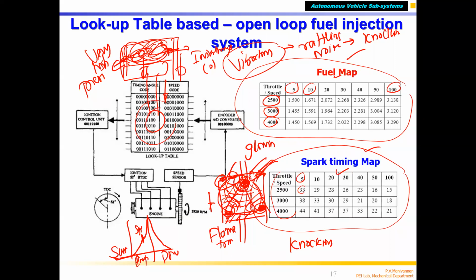Then very high pressure is created, which makes the engine vibrate. That is called knocking. If you allow the engine to run in knocking condition, your engine itself can break into pieces. So you should not operate your vehicle in knocking condition. That is one thing.